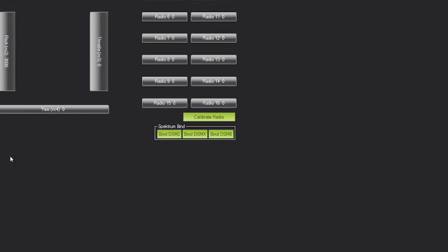On the radio calibration, I'm going to be using a remote. If you're using a FlySky remote as well, make sure that you have enabled all 10 channels, as you're going to be using them for your kill motor switch, channel number 7 at least, and that it is properly paired to your receiver so that this will work.